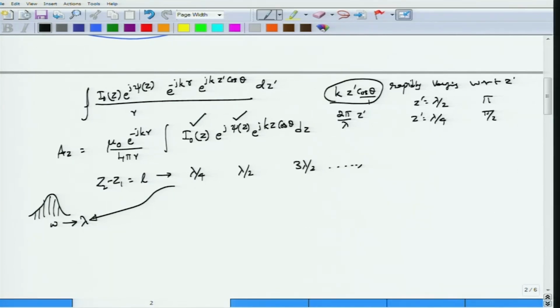So, to re-emphasize, the dipole approximation works very nicely to reduce the complexity of the expression for the magnetic vector potential. However, the central problem of antennas, which is that of estimating the current density or the current distribution, is very difficult. In order to proceed further, all you have to do is to start guessing. Okay. So, this problem is complicated, and what we do is we simply resort to guessing. What sort of a guess should we make?